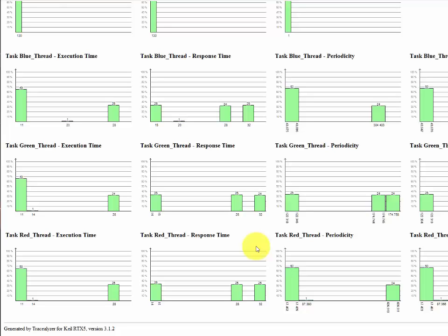And more importantly, if it doesn't do it, it allows us to dig into the details and try to figure out where potentially things could be going wrong. Once again, before, that was guesswork. We'd say, well, the system's not working. Okay, maybe it's this, maybe it's that, maybe it's some other thing. Instead, now we can actually run the system, take the trace data, and then go through and review the trace and see what's going on. Do we have a priority inversion, or a semaphore being held too long by somebody, or what's going on? We can actually start to see these details now, which can make us debug our systems far faster than we used to.